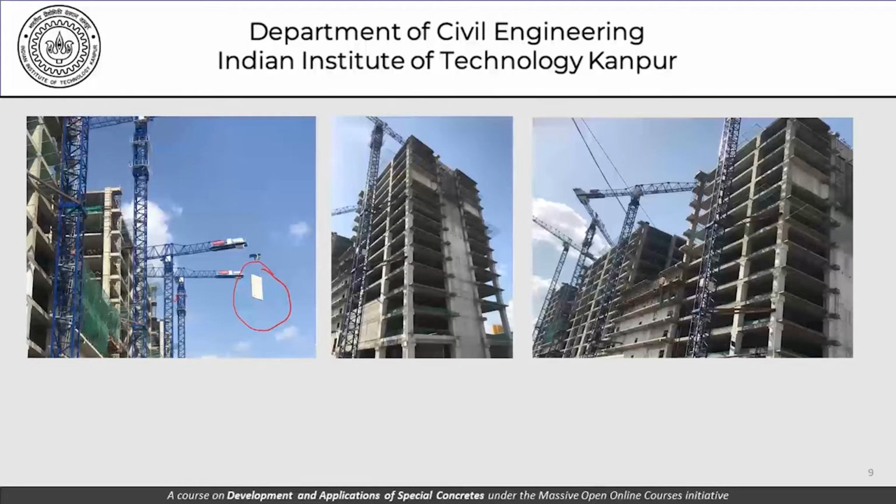Now, these elements obviously have a lot of jointing issues. So here we don't have too much construction to be done at site, as we can see from here, but there will be a lot of joints between panels. So these joints have also to be appropriately accounted for when we are trying to plan our construction sequence.